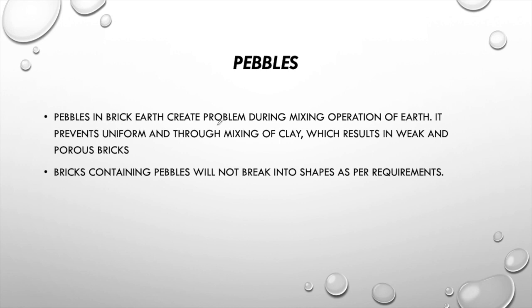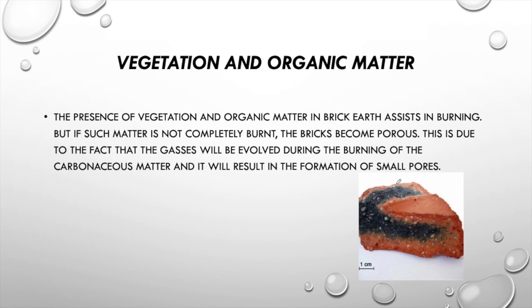Now the pebbles are also a harmful ingredient. Pebbles in the brick earth create problems during the mixing operation, and because of this it results in weak and porous bricks after burning. If the pebbles are present, then the bricks will lose their shape as per the requirement.